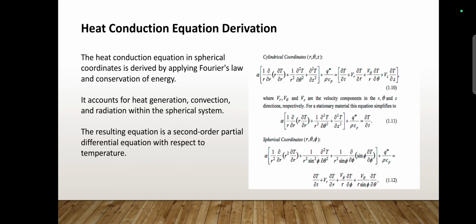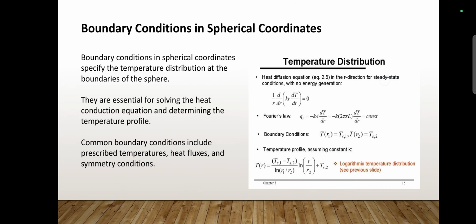The heat conduction differential equation. The heat conduction equation in spherical coordinates is derived from Fourier's law and conservation of energy. Accounting for heat generation, convection, and radiation within a spherical system, the resulting equation is a second order partial differential equation with respect to temperature.